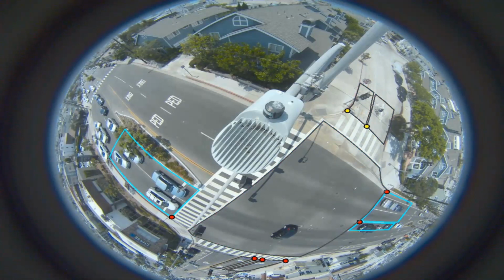So the controller logic doesn't allow you to extend a vehicle phase that's not active. So you're only extending an active vehicle phase that's in the red or in the green light status. So if you're in the green phase status and we're extending that green, if we have multiple outputs to multiple phases, we're only extending the actual green phase at that given time. So we're not really mapping any of the outputs per se in our system. We're just providing that simple call, the extension call, into the controller phase, but it's only affecting the zones that are in the green state.